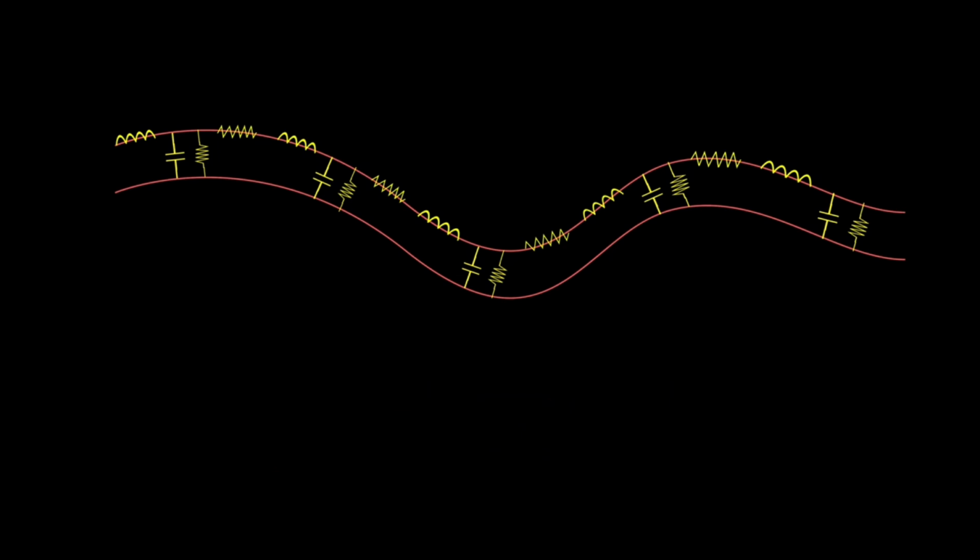For the lumped element model to be valid, the signal wavelength must be very large compared to the circuit element. We can divide the total series and shunt impedances into smaller and smaller sections of very small dimensions compared to the wavelength. Let's ignore the losses for the time being so that we can remove the series resistance and the parallel conductance from the model.